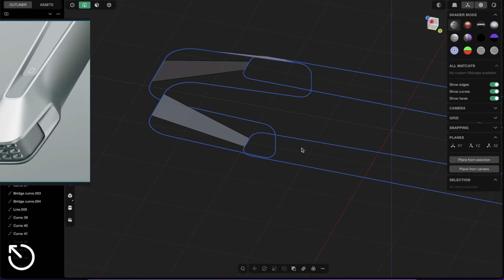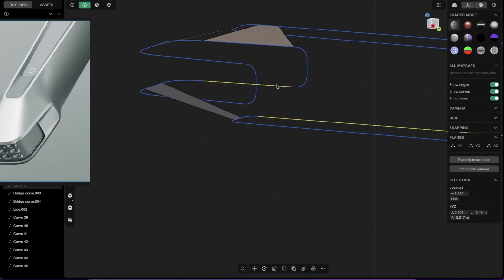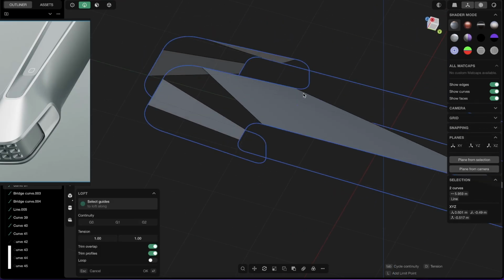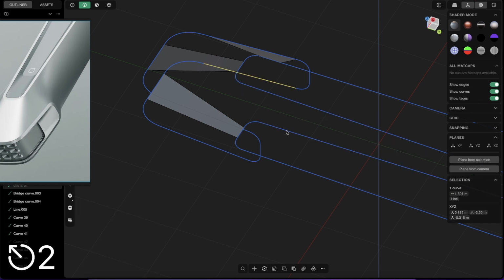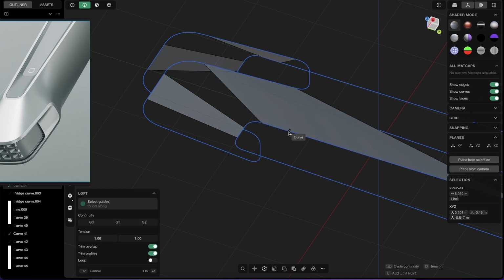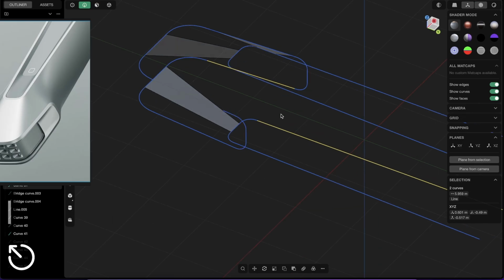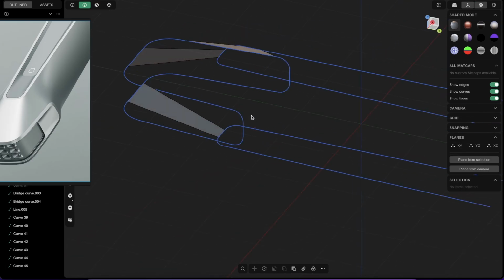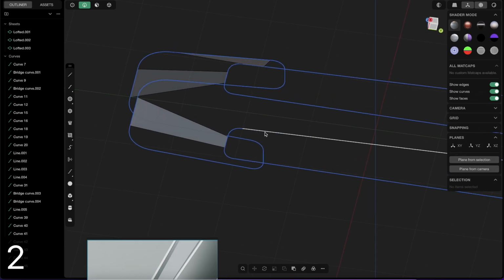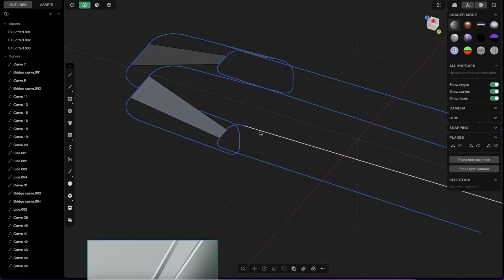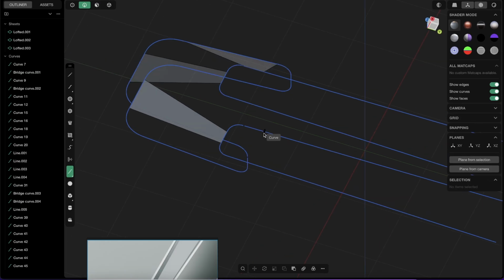So what we could try is maybe first select this one and then this one, loft, and L again, and try to add here control point curve. So this does not work. But what also very simple, you can just split this line because you see now it's just one line, but we can add here one extra point. So for that we have here somewhere split curve edge at point. So select that and just give it here.